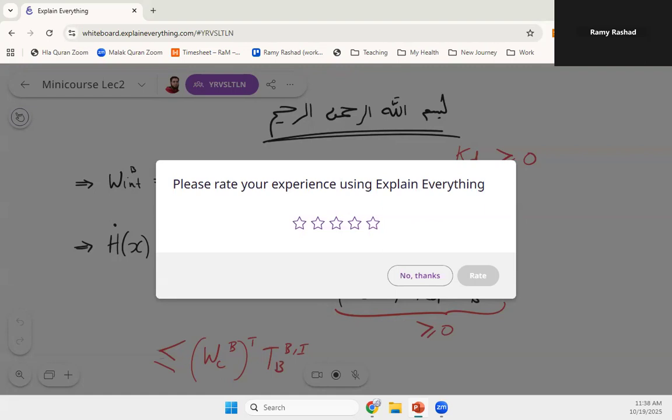These are unpredictabilities of the environment. We need to make sure that the controller itself has some way to think about the environment without modeling it. And this is where energy tanks come into place. Energy tanks give the controller, or in this case the closed loop system, a way to see what the environment is doing without actually seeing the environment. It's like internally trying to calculate what the environment is doing. Energy tanks will do this for us.